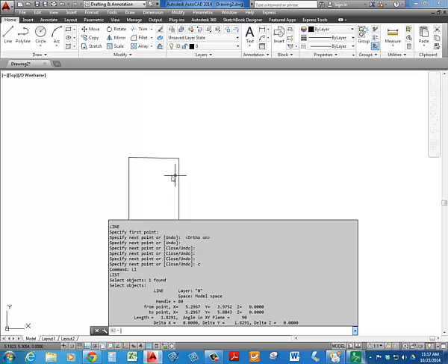So it's the XYZ location of that line, start point and end point, how long it is, the angle in the XY plane, then to a lesser degree how much it changes in X and how much it changes in Y. So if you haven't changed your angle precision to 2 places or 1 decimal place, then you can always look at delta X and delta Y. If it's a 90-degree type line, you can see if there's any change in X or change in Y. So the length of it and the delta Y for a vertical should be the same.